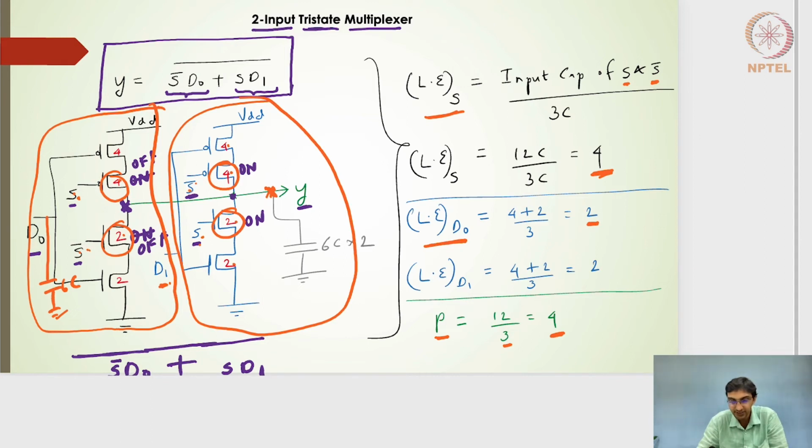And the reason is very simple: this S bar will be generated from the S signal somewhere in the circuit. Somewhere before this module, we will have an S signal directly connected to it, and S bar will be generated from an inverter. If we don't know the size of that particular inverter, it's better to take its sizes here in this module.